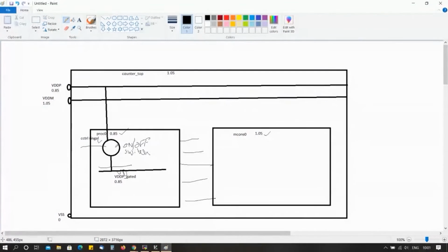So if it is in the off domain, then what will happen? Whatever output signals are available here, everything will have some random value, some dump value. So whatever the connections to the other block, those dump values will be processed. So you need to provide some constraint so that when this block is off also, the communication should not be disturbed. It should not change any functionality.